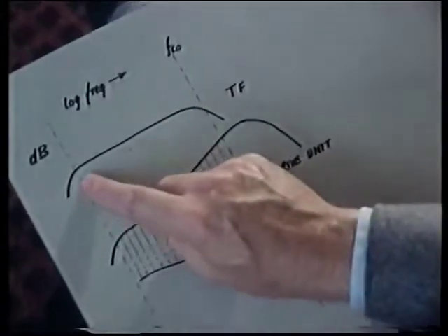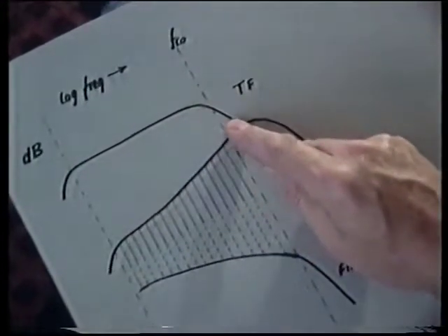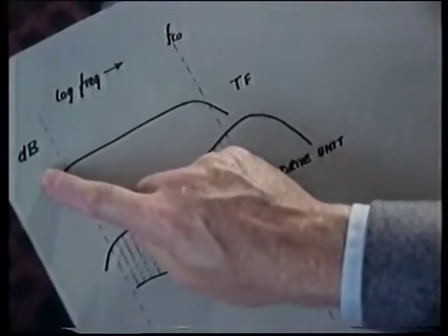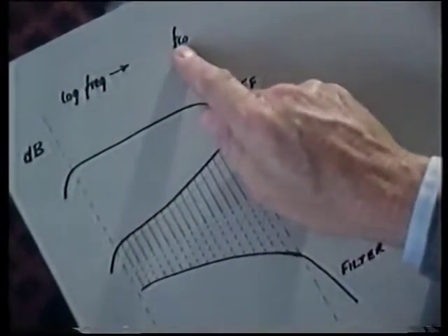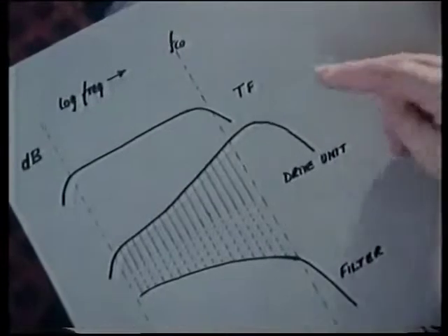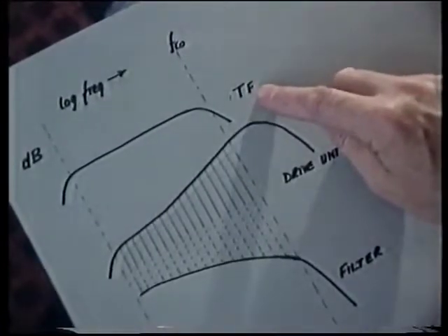Now, hitherto, this has been done very much by cut and try methods, and not always very satisfactorily. But with modern computer techniques and using impulse response methods, we can do it very much more accurately and certainly very much more quickly. We begin by postulating a required frequency response in terms of sound pressure, given here in dB, against log frequency. And we call that the target function, because that is the response with which we want